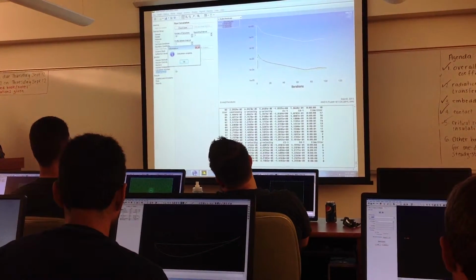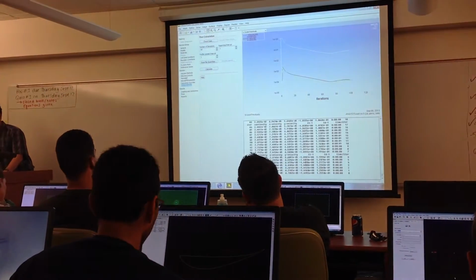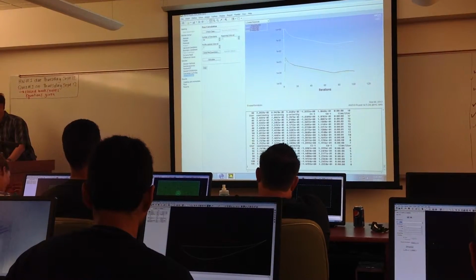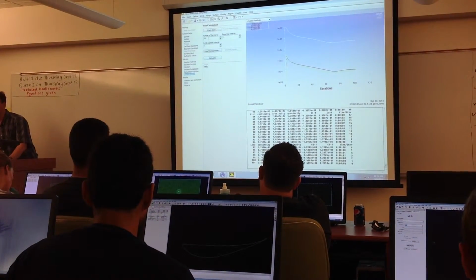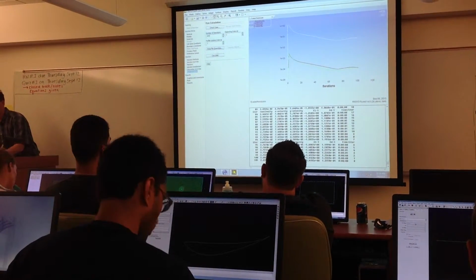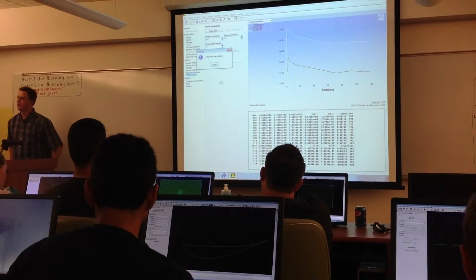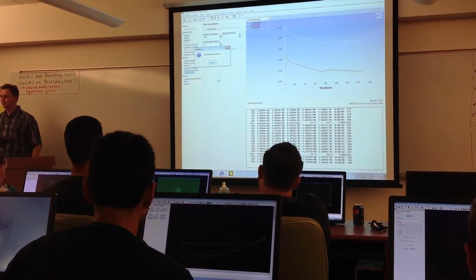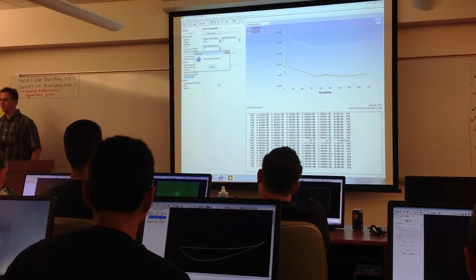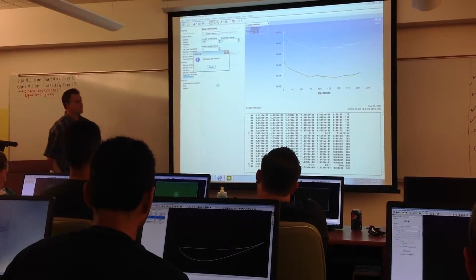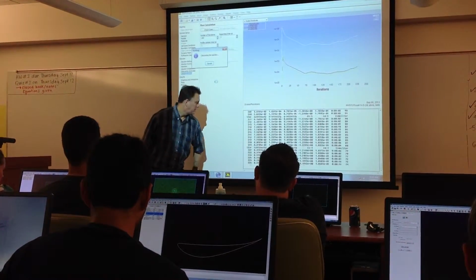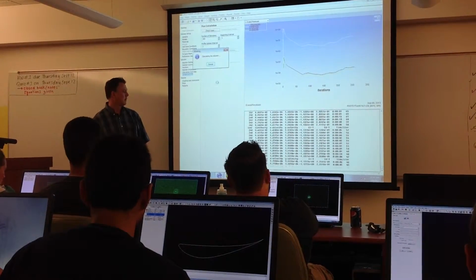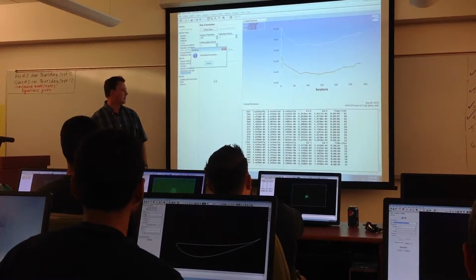Now I'm going to go ahead and turn on the second order. Well, let me not do that just yet. We'll run this a little longer, see if I get a convergence. See, the residual is going back up for the continuity. Actually having a lot of problems there with the continuity. You can see that.